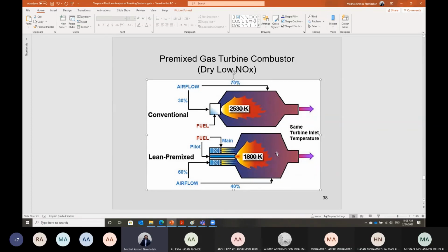There are different techniques, and also to use Oxy Fuel Combustion technology, which is one of the carbon capture technologies, in which we burn using oxygen plus some recirculated carbon dioxide. So it is nitrogen free in this case. That means if we have a gas turbine adopting Oxy Fuel Combustion, we should not have any NOx emission, and the gas turbine should be NOx free.